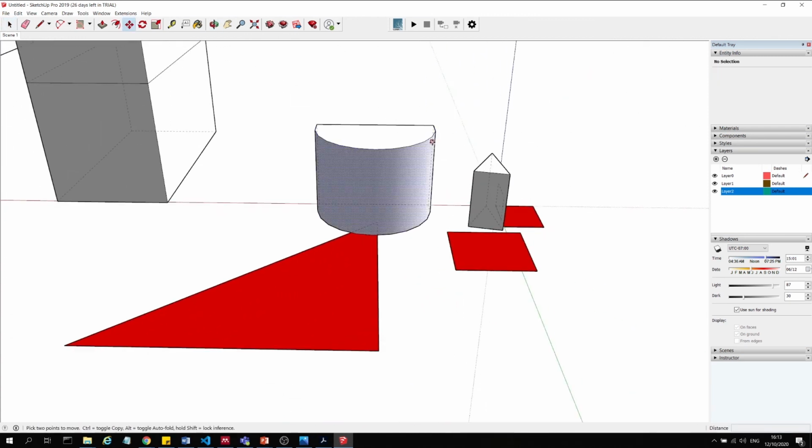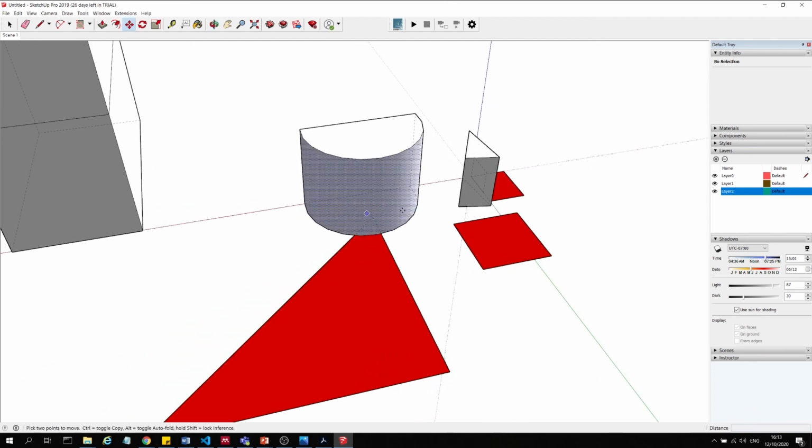That's because SketchUp, despite reading this as one surface, which is made out of multiple surfaces, but you can see here it displays as one surface, won't really assume that the two geometries are connected if the face interferes with the face, but if the edges interfere with edges, again, it'll think they're linked. So here you can see this is what's happening because we have edges connected to edges.